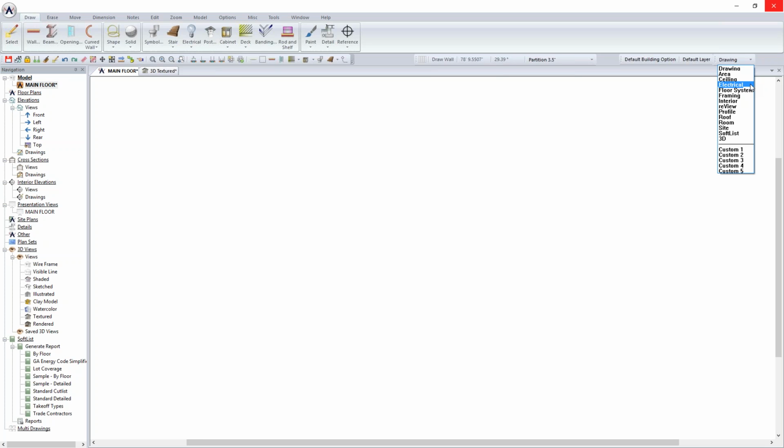Okay, so we are going to teach you to basically draw with that in mind. One main floor plan stores all of the information. Okay, so that's basically, again, menu bar, ribbon bar, toolbar, status, and then you've got your options, layers, and visibility controls. Down the left-hand side is what's called the navigation menu, and the navigation menu is something we're going to reach for plenty in the coming minutes here.